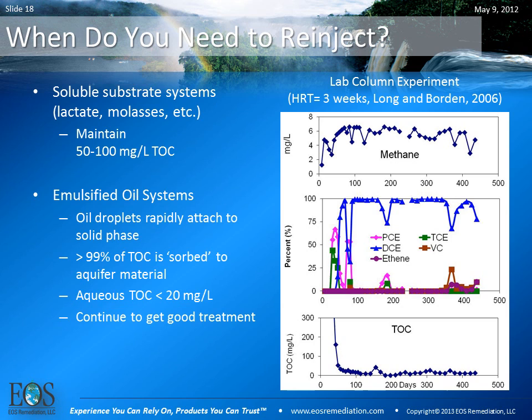And in order to maintain longevity, you would obviously have to maintain a lot of TOC. And so that's why these re-injections are required. You need to maintain anywhere from 50 to 100 milligrams per liter TOC to just keep that system going.